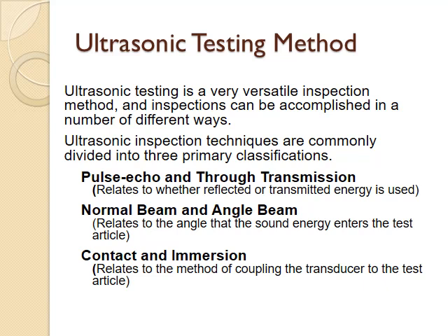There are 7 methods available to check the condition of the material by using NDT: visual inspection method, liquid penetration method, ultrasonic flaw detection technique, radiographic technique, eddy current test, magnetic particle testing, and thermography. Of these methods, let us discuss the pulse echo method only in this video.